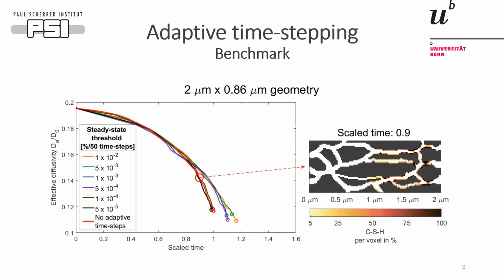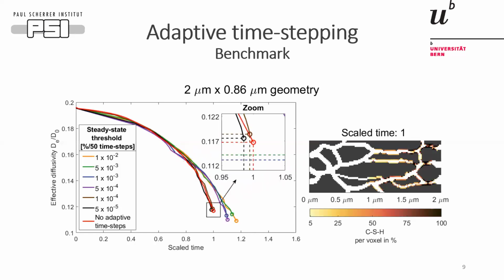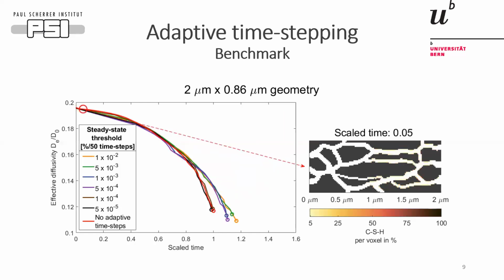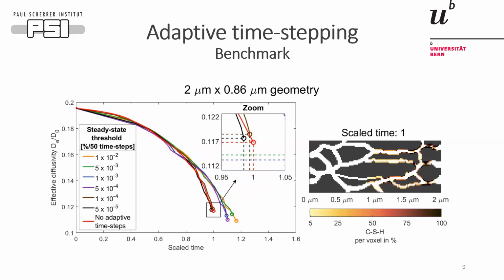Important to mention is that for the simulation of diffusion, the shield porosity of CSH is taken into account. So the CSH precipitates will lead to an evolution of the microstructure, which can also steadily reduce the effective diffusivity. And because the shield porosity is considered, it will not reach zero even after total clogging.